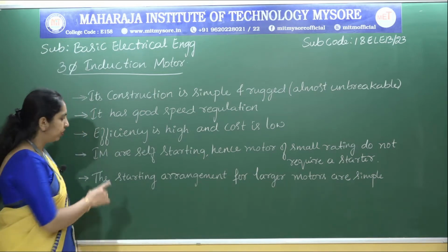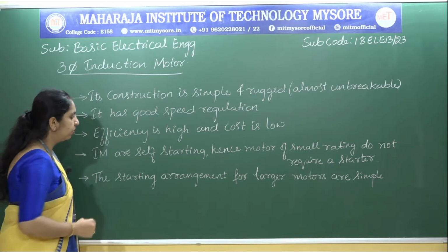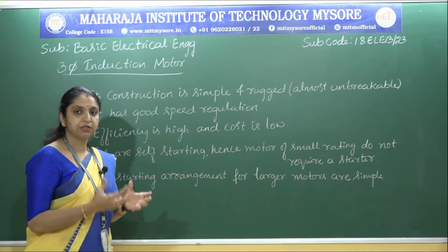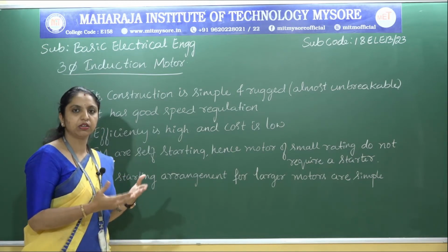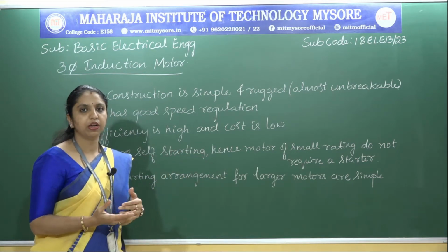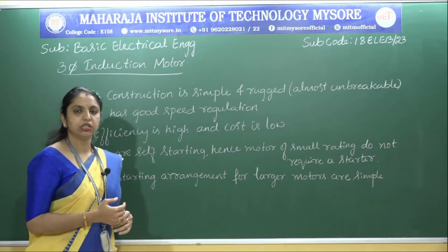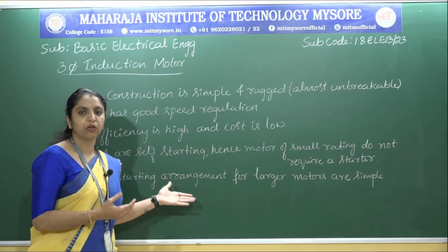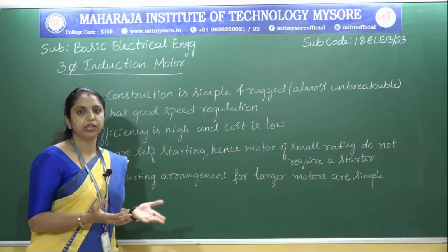Next, wherever I mention IM, it indicates the induction motor. Induction motors are self-starting, so they have a self-starter. Hence, motors of small rating do not require a starter. And the starting arrangement for larger motors is simple. As I have indicated, these are the reasons why the three-phase induction motor is extensively used out of all AC motors.